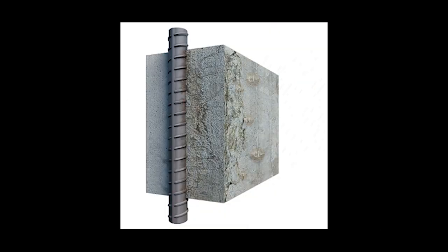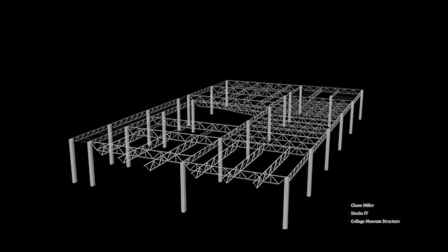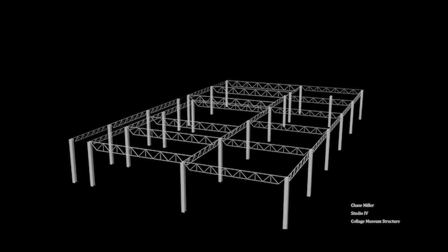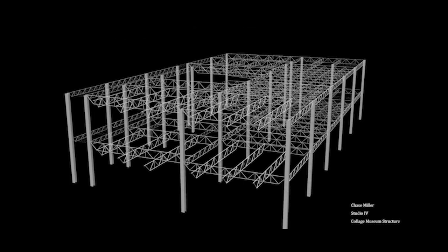The reinforced concrete core acts like the main stabilizing spine of the building. It carries vertical loads and helps resist lateral movements. The steel exoskeleton and trusses provide additional support, especially against the wind forces. Since the building has a curved sail-like form, its shape helps reduce direct wind pressure by allowing wind to move around the structure.